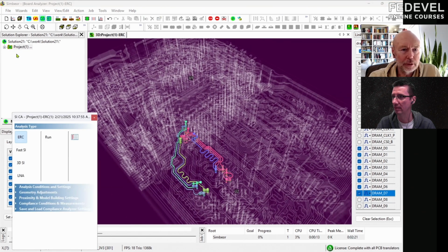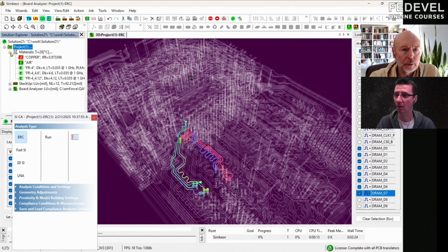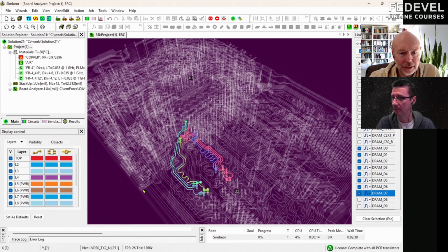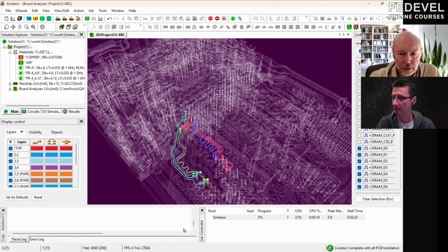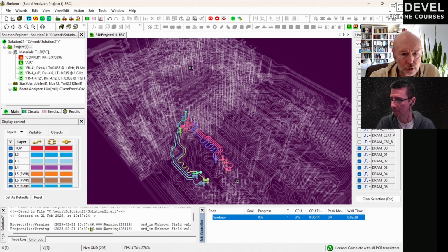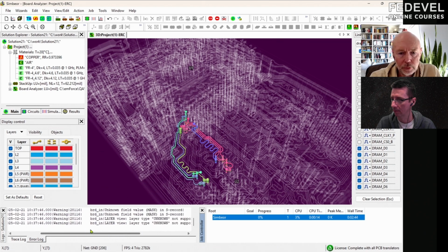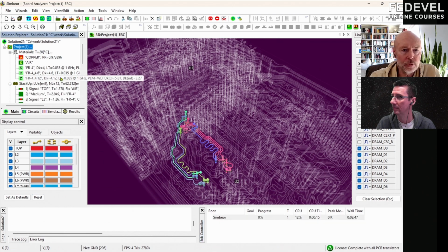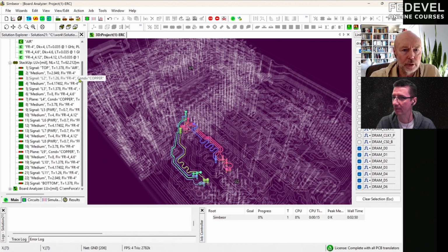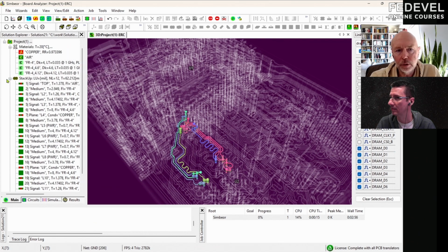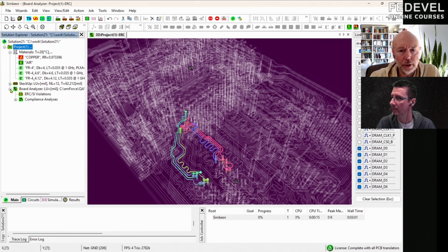The stack up was imported. Oh, with the board file. Oh, cool. Exactly. It may not be exactly what it is. So, for instance, right here, it generated a few error messages, warnings. No, it was exactly as it was specified in the board file. Okay, cool. You can see it right here, the whole stack up with all those numbers. It looks like the dielectric constant is 4.6, which is a little bit high.